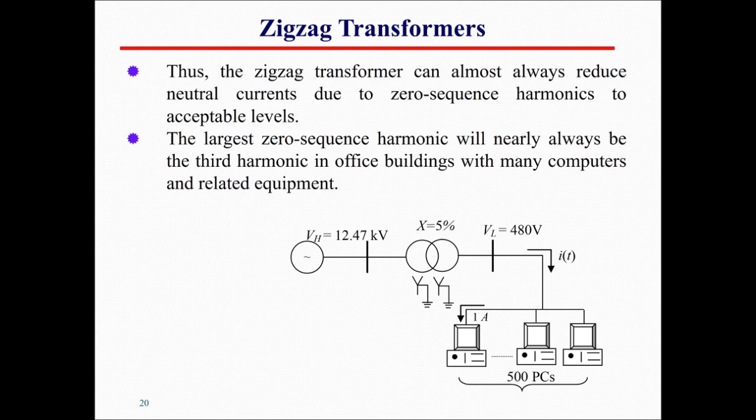As a result we can use a zigzag transformer connected on the secondary side. It has to be near the load, and that will take care of this problem.